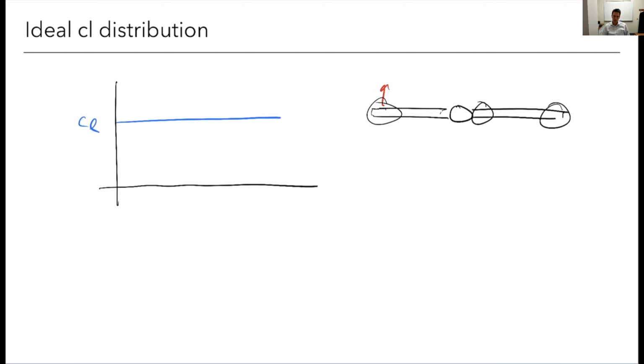That's not happy for the passengers. It's not happy for piloting. There's no people, but it's not happy for an uninhabited aircraft either, because I need to control this. So I don't want tip stall. That's in contrast to if the lift was at the root, right? And then I get a stall, one of them drops off. Well, that's a much weaker rolling moment that's going to occur. That's not going to upset my balance very much. So I really don't want tip stall. That's something I have to be careful to avoid.